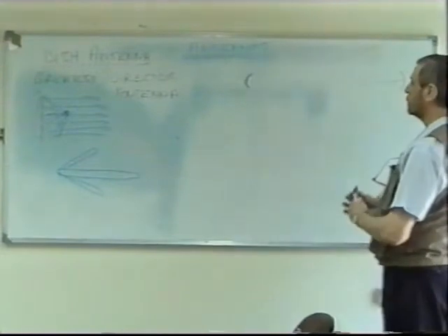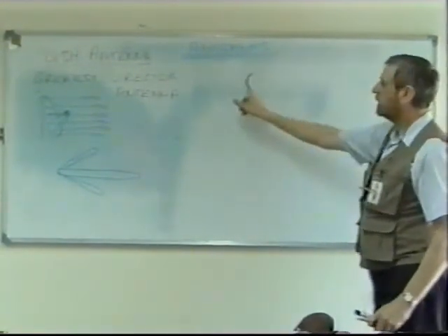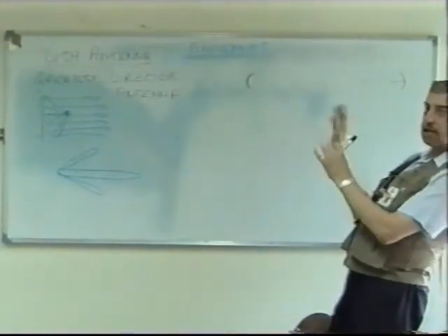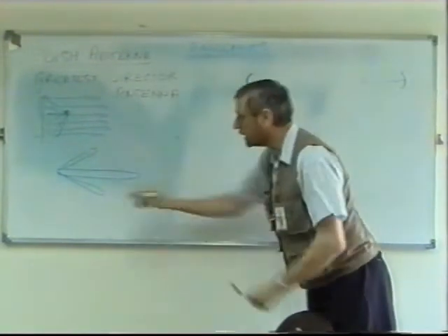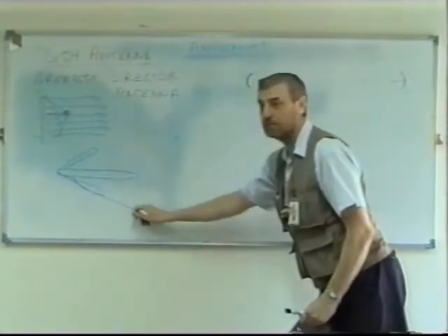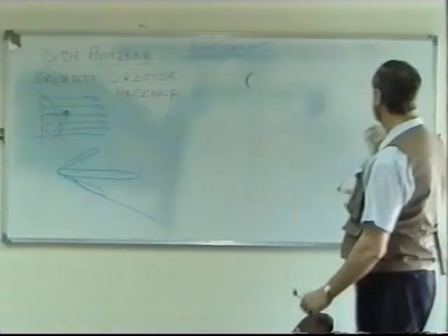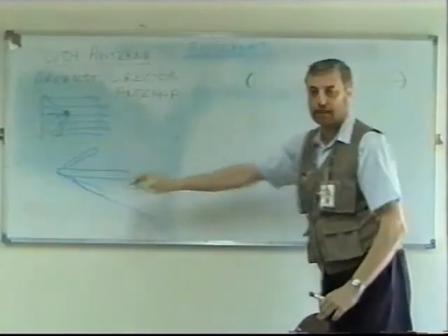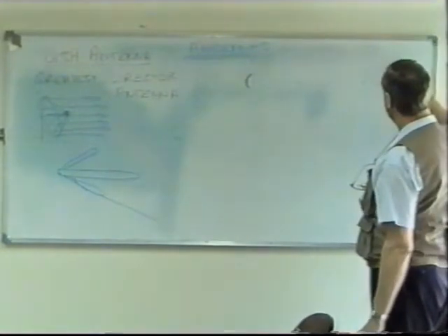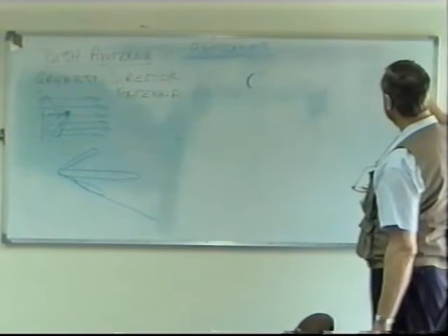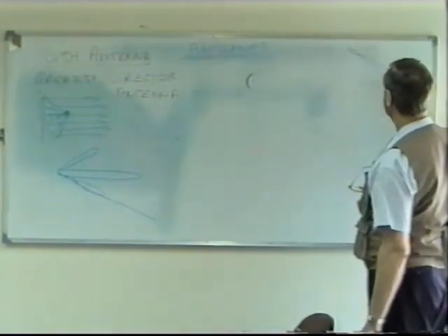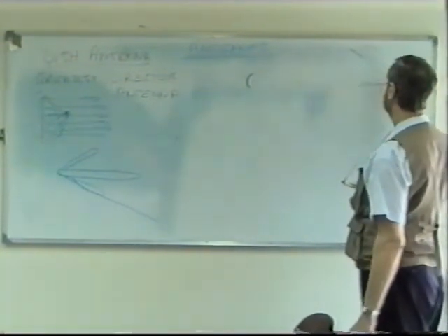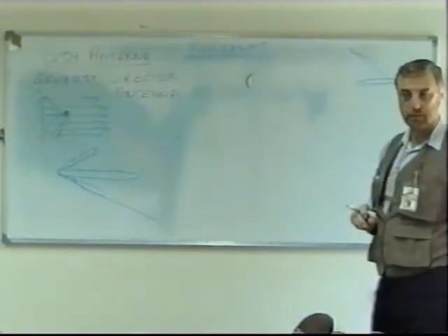And it's not unusual to tune your microwave and think, I've got everything aligned, but what in actual practice you're doing is running on one of these side lobes. What you've actually done, as you move this dish, it's a bit like moving this polar diagram around. And by moving the dish by a small amount, I'll exaggerate it a little bit, your main lobe is pointing up here somewhere, and what you've actually done is tuned your microwave onto a side lobe.